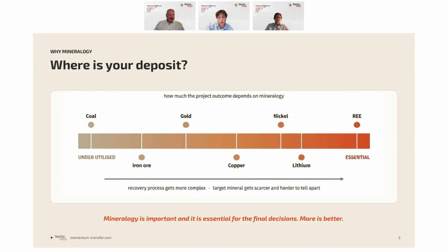And then when we get to copper, nickels, we're looking at sulfides versus oxides, what sulfides we have, what phases we have. It makes a difference if we're going into a mine and for flotation. And then also in lithiums, where we want to understand exactly what phase is hosting the lithium. And also we might be surrounded by more clays, and in clay-rich areas, it's very important to tell how clays act under certain conditions for when we finally go through onto our metallurgy test work.